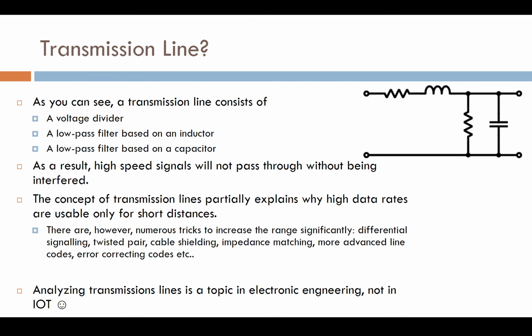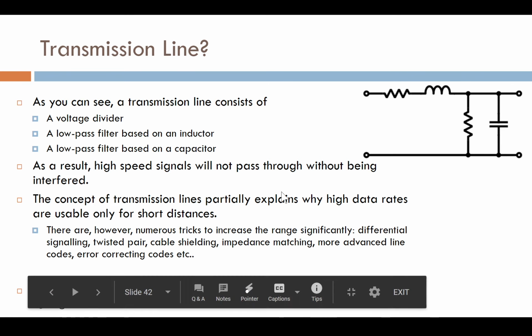And in addition to that, the third part of this one is the ringing, because this here is an oscillating circuit. This oscillates. We haven't gone through the oscillation on RL circuits in that sense, but that actually will oscillate because this inductor and this capacitor have the phase shift on the current. So when current flows that way, the voltage here goes higher. And if it doesn't go here, basically it comes back and this circuit oscillates a bit.